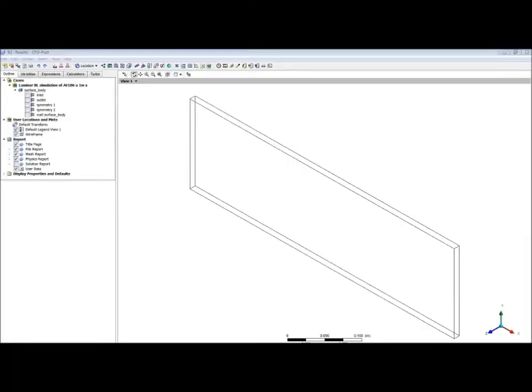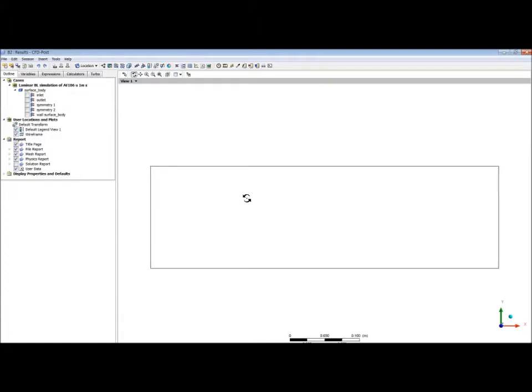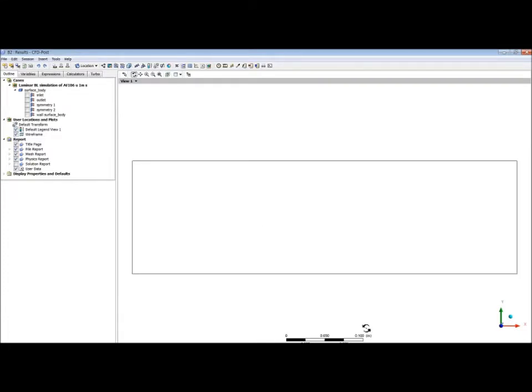So there we are, CFD Postprocessor has opened up, and this is what we get in the first instance. Just a quick note about the CFD Postprocessor. It's mainly designed for looking at 3-dimensional fluid flow. So when it gets a 2-dimensional flow, like we've just done in Fluent, it actually extrudes it slightly in the Z direction. So therefore you do have this additional extruded surface. If you align that to the Z-axis and look down onto the YX plane, we can see that we've got the inlet, the outlet, and these 2 symmetry faces, and then the wall bodies on the top.